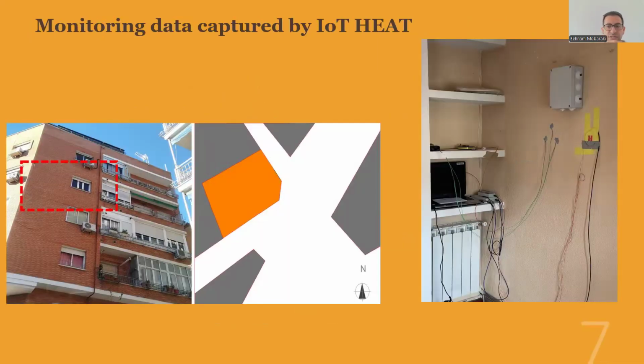This study addresses thermal bridges, these gaps, by employing a finite element method based digital model to analyze thermal bridge performance in a representative building envelope located in Barcelona. In addition, in situ thermal monitoring was conducted in a residential building to investigate thermal bridge behavior, and finally the collected data were used as an input of the FEM model.